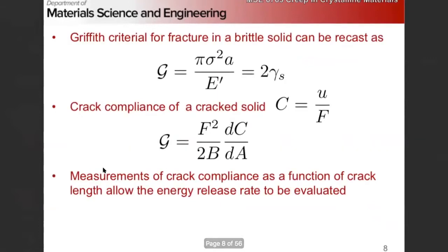Can you get one from that? How do you go from that equation to this equation? You don't have U in the first one, right? You have crack. Yeah, so you need to go through your elastic theory, right? So it's not only that equation. It's not. Well, yeah. You write stress as a function of strain displacements, right? You use isotropic elasticity, so you can write this in terms of displacements. It's not straightforward to go through.